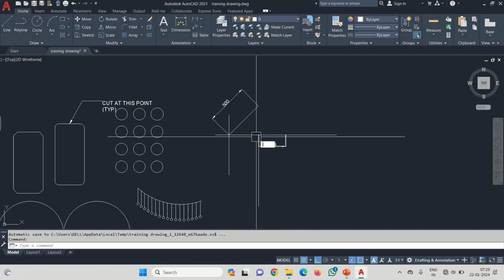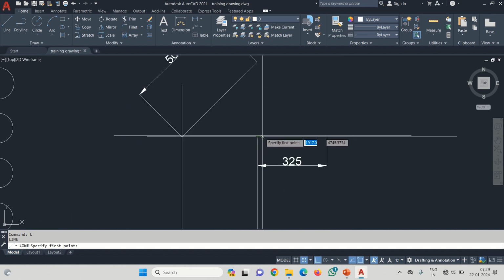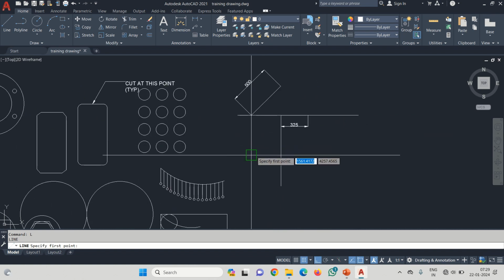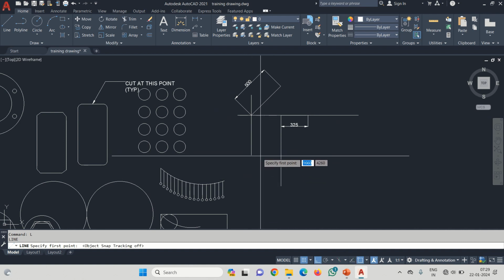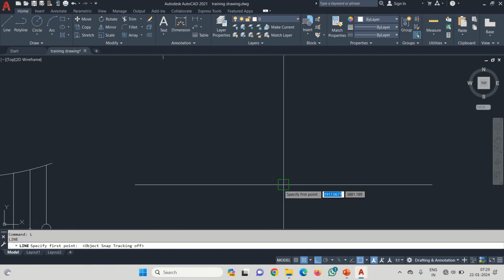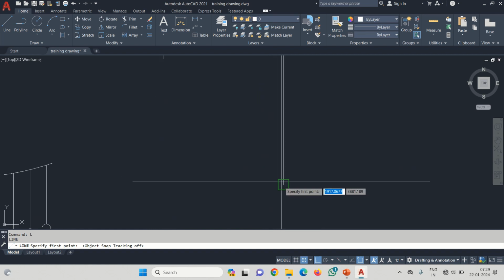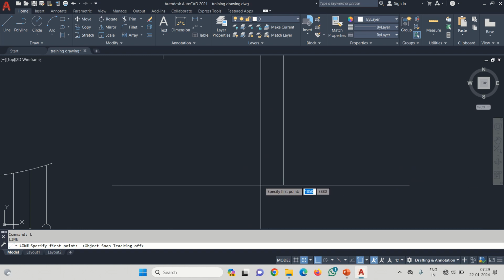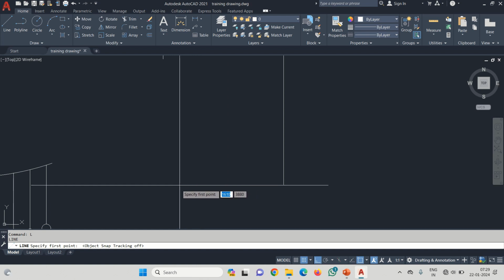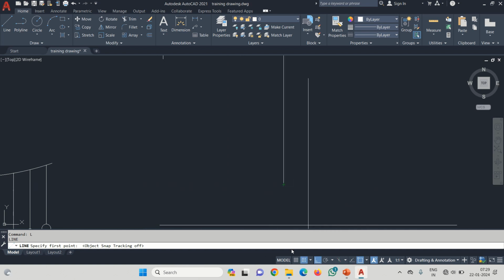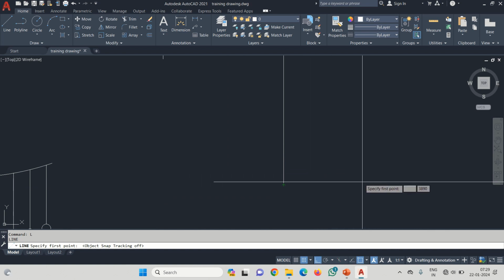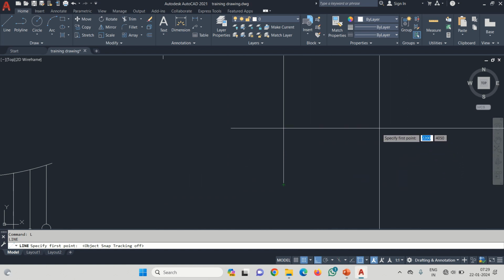So now when I select the point and move the cursor, it will move 10 mm, 10 mm. Let me click and remove this. If I click here, it will move 10 mm, then 10 mm, then 10 mm, like that. You can see 1670, 1650, 1640, so it will move in those directions only. Because we have put snap on, my cursor will move 10, 10, 10, 10.